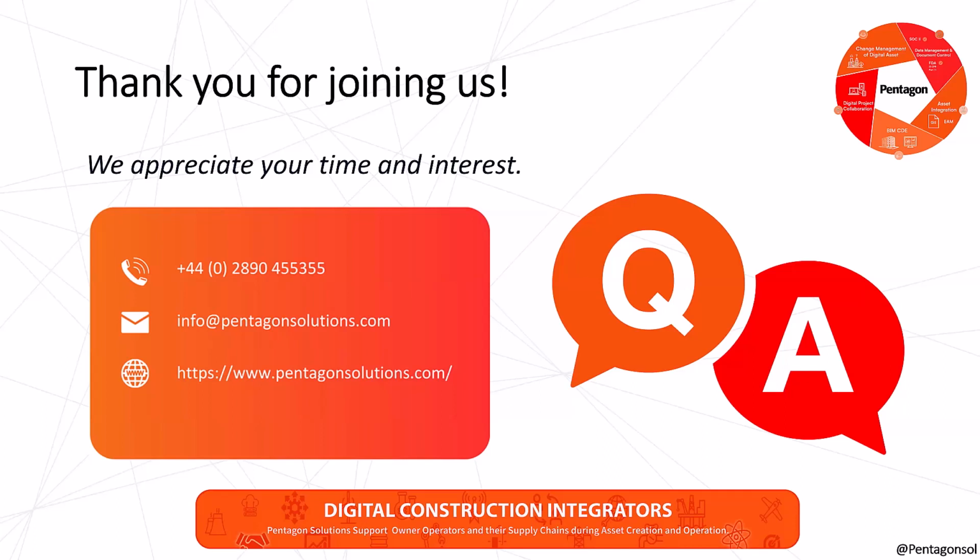Yeah, you are able to coordinate your Tekla scale within your project. There will be different methods involved in that. Obviously, the major one is it's easy for anybody to really move and link a file into the correct position. But like you say, we haven't got the shared coordinates from that. The main thing is looking at what is the integration process initially from your IFC file to Revit. Has the project base point been initially set up in that instance? Although the file does become quite large, again, it should be used as a referencing file.